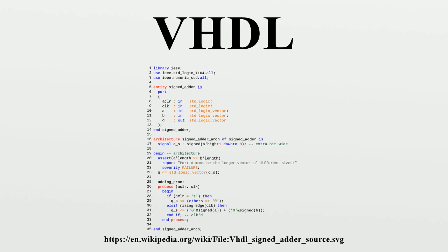Another common way to write edge-triggered behavior in VHDL is with the event signal attribute. A single apostrophe has to be written between the signal name and the name of the attribute. DFF: process begin if RST = 1 then Q <= 0; else if CLK'event and CLK = 1 then Q <= D; end if; end process DFF.